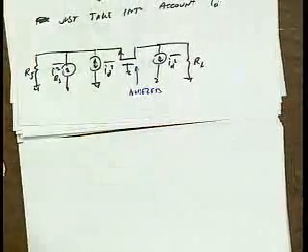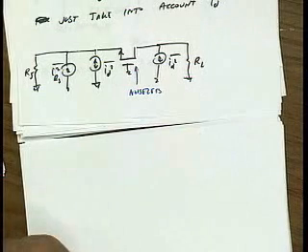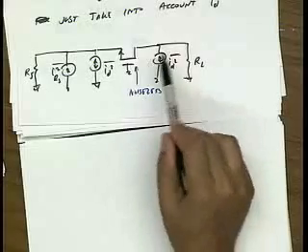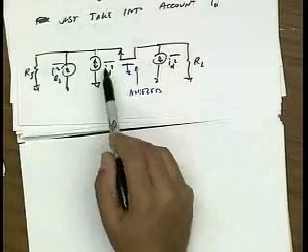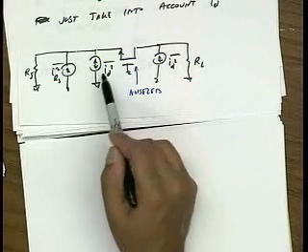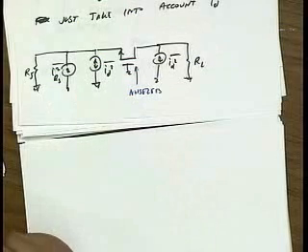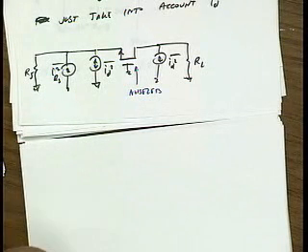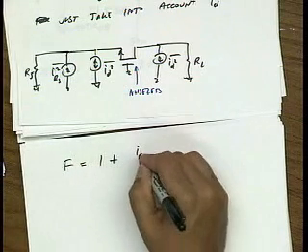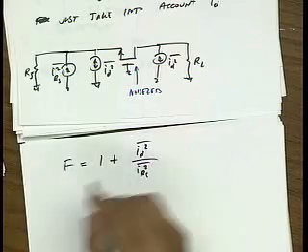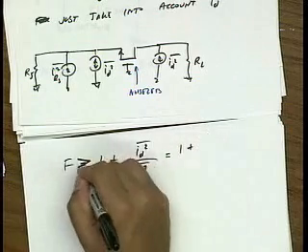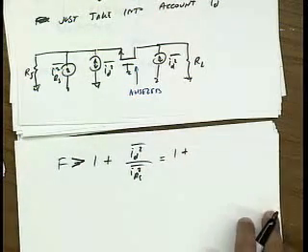All right, well, again, I want to make things as simple as possible. For a moment, forget the fact that you have this noise here. Just focus on this noise. You can see that if this were the only noise in the system, the noise figure would be basically 1 plus the ratio of these guys, right? Because they're competing with each other. So the noise figure would be 1 plus iDrain squared divided by iRS squared. Okay? In other words, it's 1 plus, so let me say greater than. We're finding a lower bound on the noise figure.